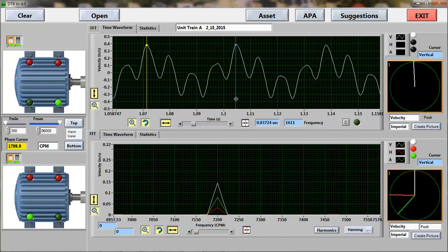And right at the peak, assume this is just a full cycle. And in fact, it's almost 1800. Here's our frequency and the time duration between the two cursors. And in fact, it is. And therefore, these would be multiples: 2 times, 3 times, whatever they turn out to be. This is another handy tool. It takes a cursor, centers it, you drag it to your given peak, and all the corresponding cursors will match out.